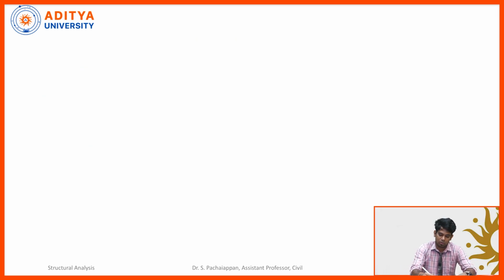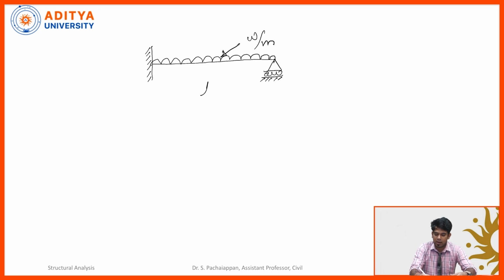Now I am going to explain, in the first slide we have seen, the procedure to calculate the prop reaction that we are going to discuss. So let's take the cantilever beam, and then at the end I am having another support, which is the prop. Let's consider this beam is having a uniformly distributed load, UDL, of intensity W per meter, and the span of the beam is L. Give some names also: this is A and this is support B.